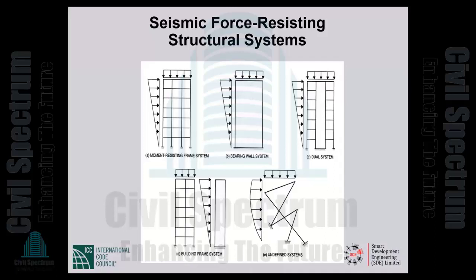Okay, shear wall by definition is a wall that carries gravity as well as in plane, as opposed to out of plane, lateral loads. So in a bearing wall system, shear walls carry 100% of the gravity and 100% of the lateral forces, the same shear walls.